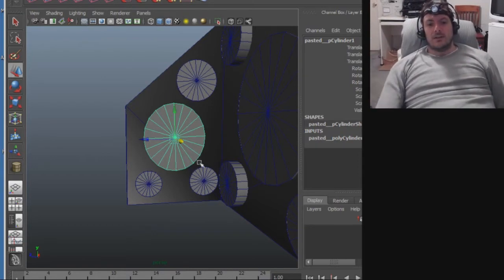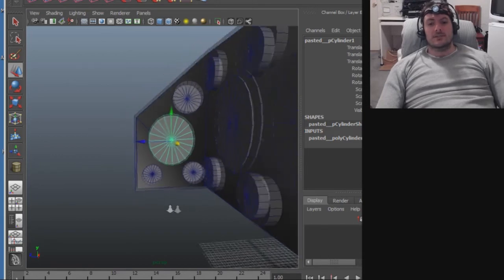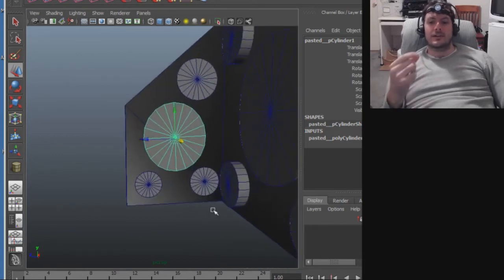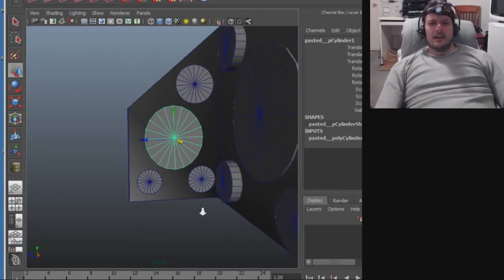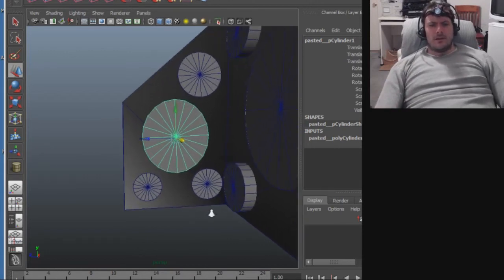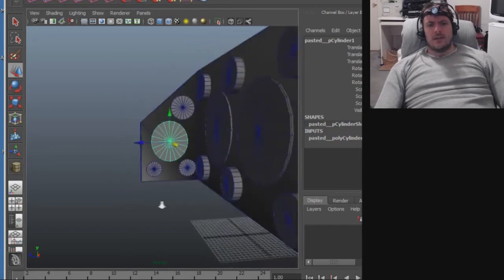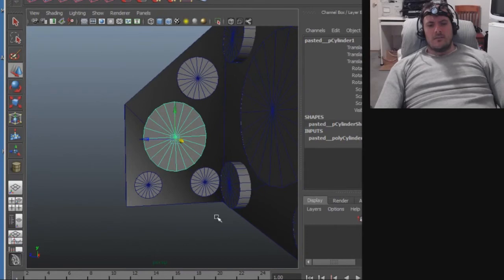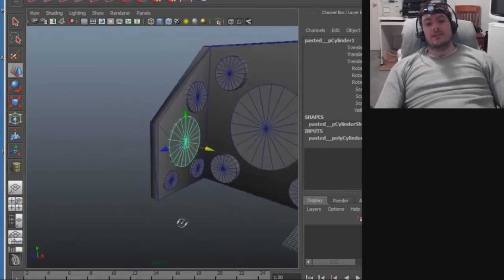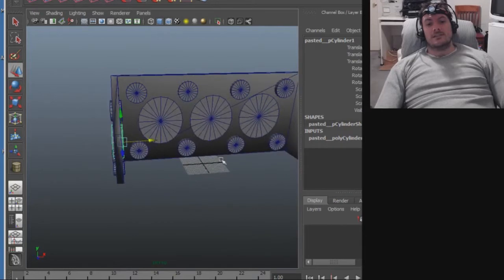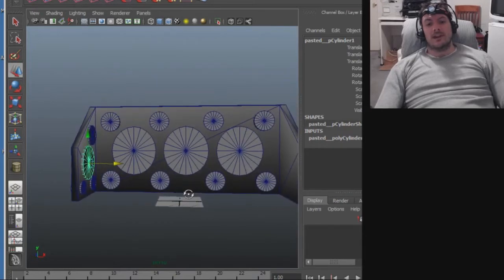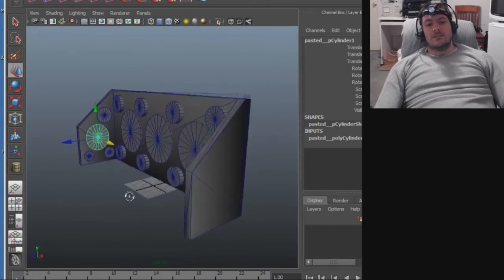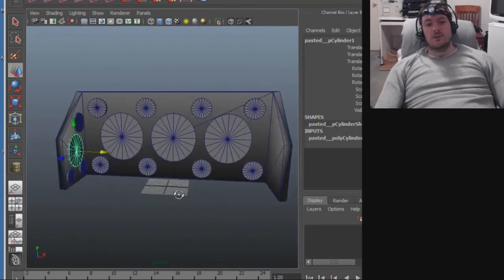So I'm going to fill in all the circles as if there were dents on a car with Bondo, and then I'm going to sand it. And I'm not using Bondo, I'm using ABS slurry sludge, which is acetone and ABS mixed to create a thick sludge, like peanut butter consistency. So that will be my spackle. And I'll fill all these holes manually, which will get rid of a lot of my scrap ABS from failed prints. And it will save a ton of printing time because everywhere you see a circle is less printer filament your 3D printer has to use, which means your 3D printer doesn't have so much stuff to print anymore.